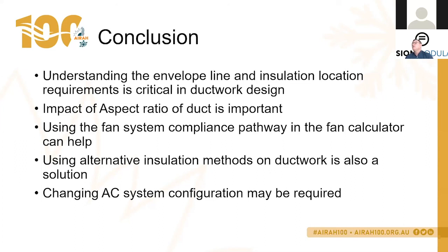So can I confirm rigid duct can be used between the 6 metre, say you go 3 metres of flex, a bit of rigid duct, say to get through a firewall or a penetration or whatever that you need to get through, and then you put another 3 metres of flex on. As long as it's in accordance with the Australian standards and the ductwork standards and the code requirement of a maximum of 6 metres of flex, then it's up to you as a design engineer to determine that that's acceptable.